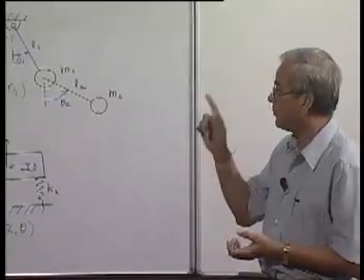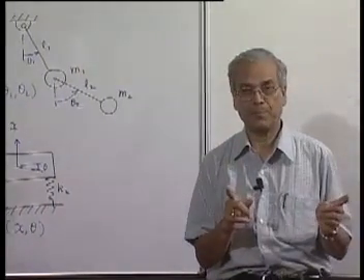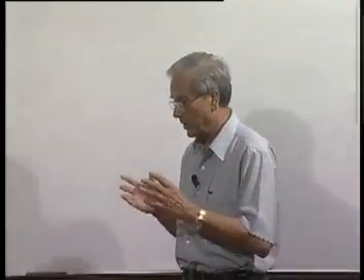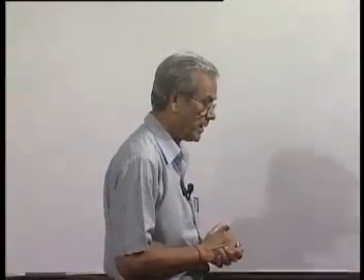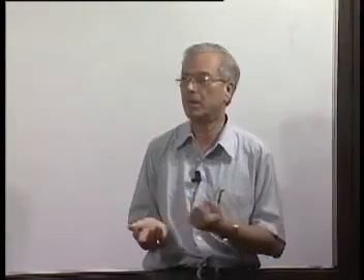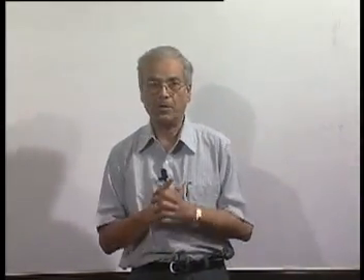On the other hand, it is possible to give the initial conditions to start the motion of a 2 degree freedom system in such a way that both the bodies will execute simple harmonic motion, and we will see that when one body is executing simple harmonic motion, both the bodies are executing simple harmonic motion, and the frequency of that oscillation for both the bodies is the same. Phase difference can be there, that means they can be either in phase or out of phase, as we will see later, but the frequency of oscillations will be the same and both will execute simple harmonic motion only for some specific cases where the initial conditions are adjusted properly.